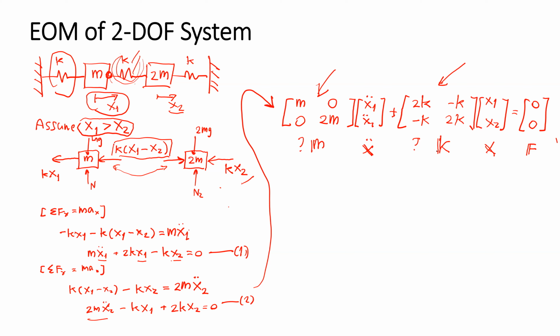In some complicated systems that have a damping matrix, the equation of motion may be written in the form of the inertia matrix M times x double dot, where x is a vector, plus C x dot, plus the stiffness matrix K x, equal to F, the force vector. And the vector x is also time varying, depending on the time t.